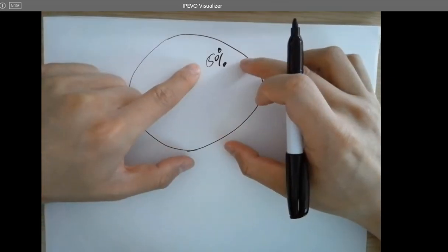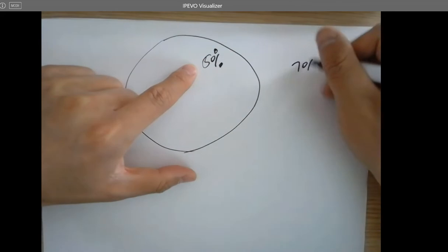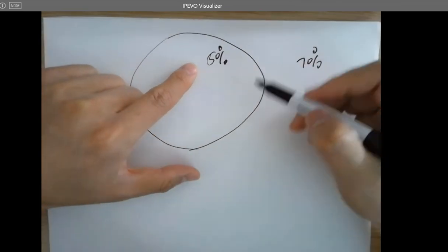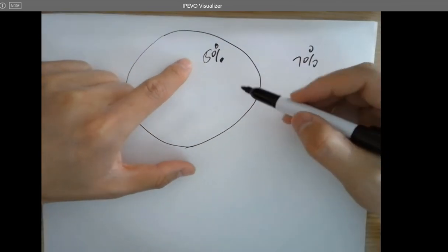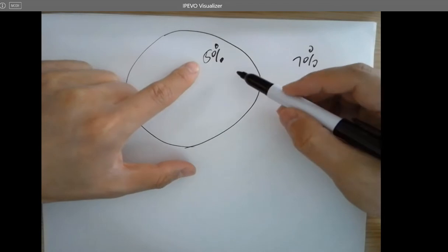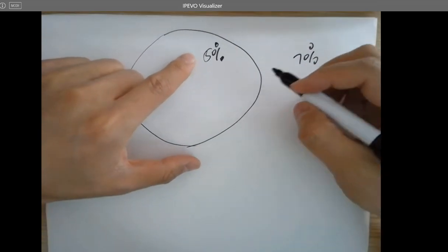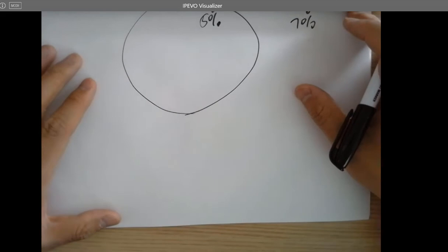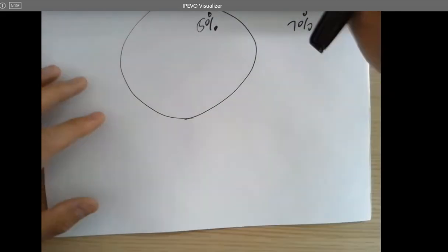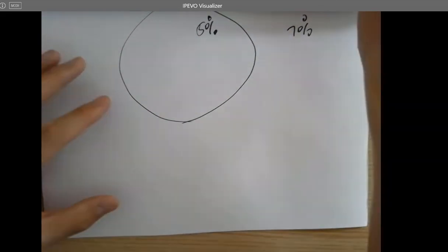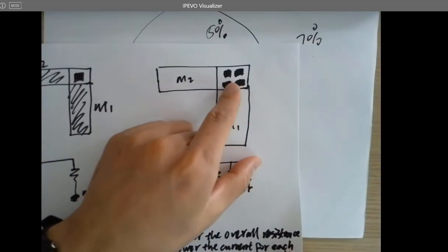So the yield is low. But TSMC probably has 70% of the chips on each wafer functioning. So yield is a critical parameter in the semiconductor industry. There are many ways to improve the yield. Having a via array is one of them.